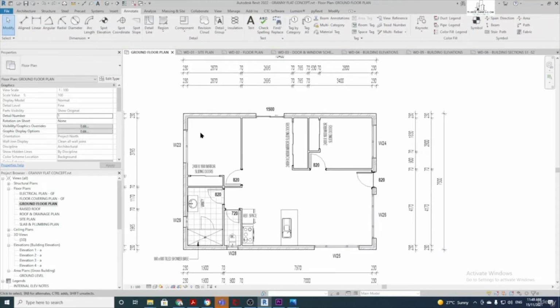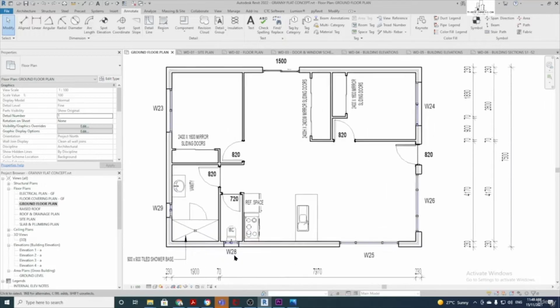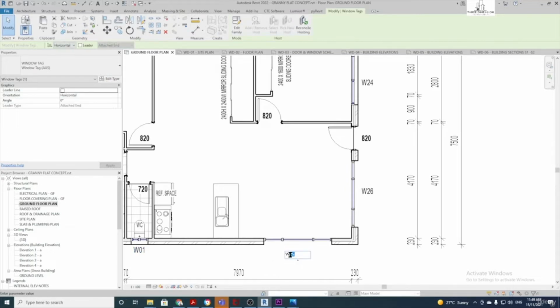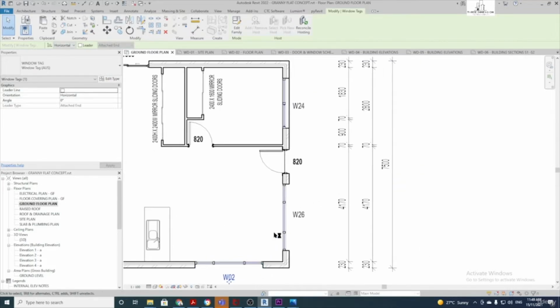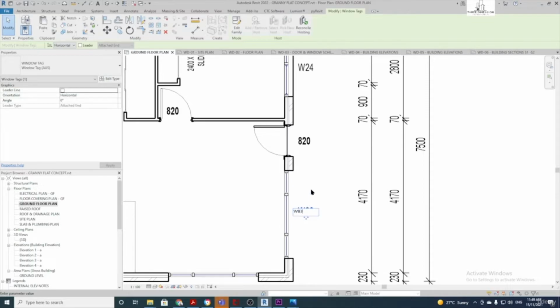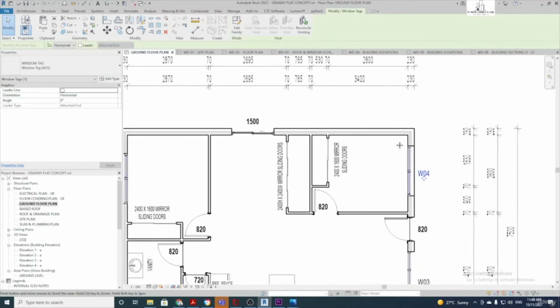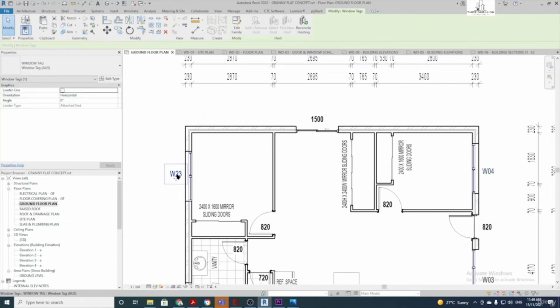2. Okay, yeah, so for all our window numbers, we can renumber all these so they start with number 1. So come down the bottom here, change this to W01, double click on them, W02, click on this one, W03, W04, just go around renaming the sequence, W05.